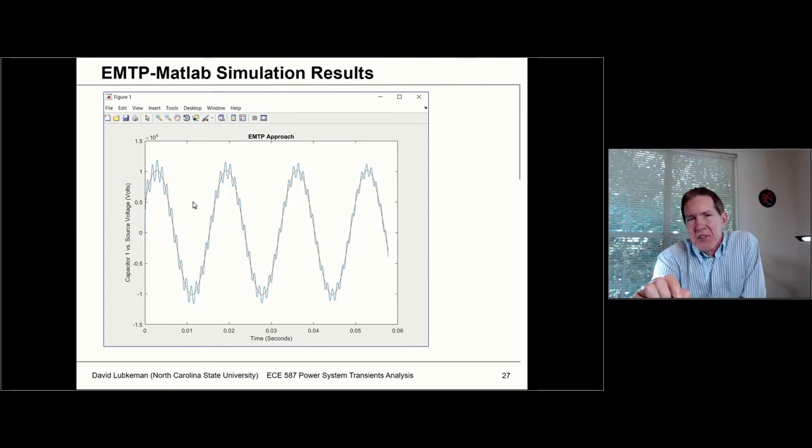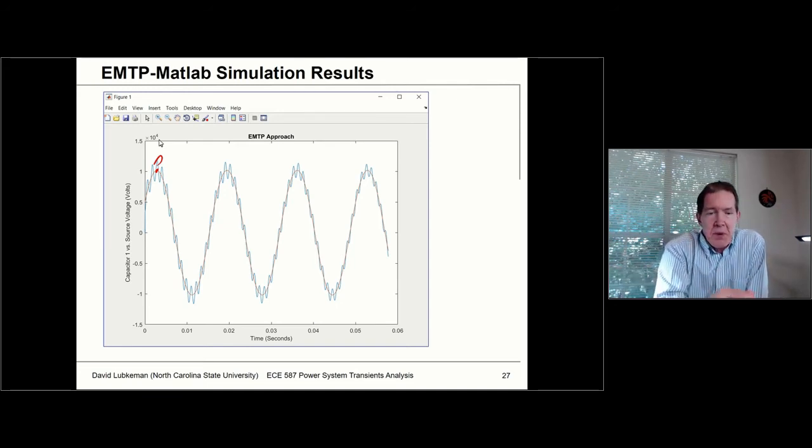Since I have very little damping in this circuit, it's going to take a long time for this transient to decay. But what I'm really interested in is what kind of stress this is going to put on things. When you superimpose this on top of the forcing function, you see some additional stress which is going to be put on, say, a customer load connected in parallel at this particular point in time.